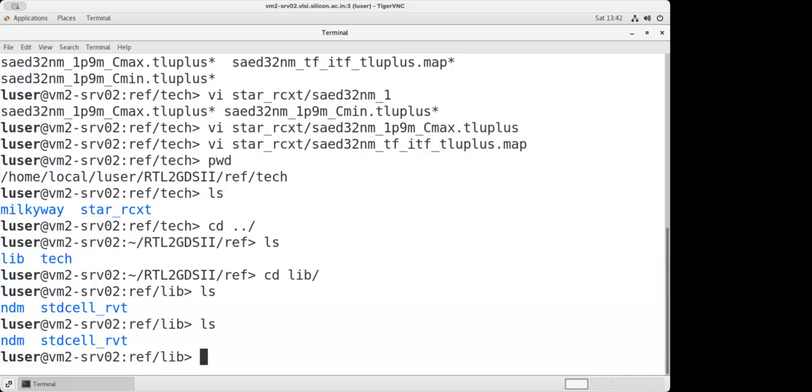So the answer to your question is, it's not a universal rule that if you go to the top layer, or the next layer, the resistivity is going to be different. The TF file which I showed you, in that the stack was like 6, 7, 8, it has the same resistivity. Maybe the top layer, the resistivity is going to be different. You can check that once everything is up there.